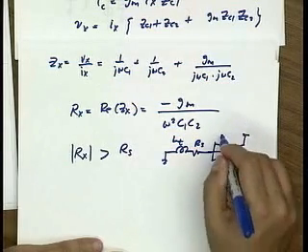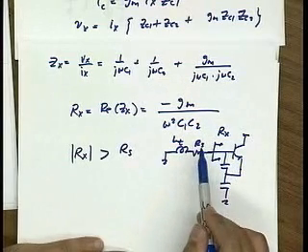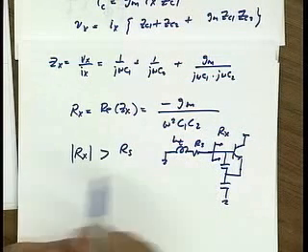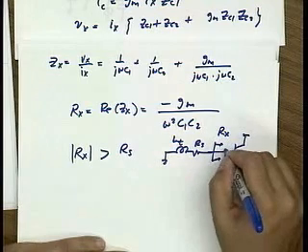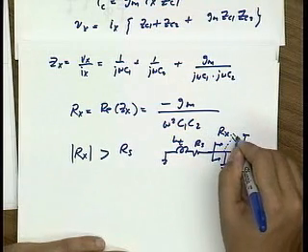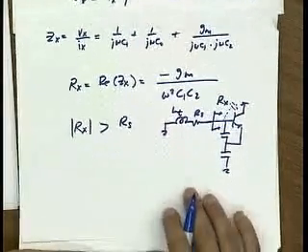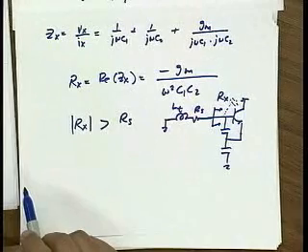Looking into here, Rx should be bigger than Rs for startup, and LT should resonate with this series combination. Now again, just as before, you can include C mu later. It's pretty trivial to include C mu in the calculation. And as before, C pi gets absorbed into C1.